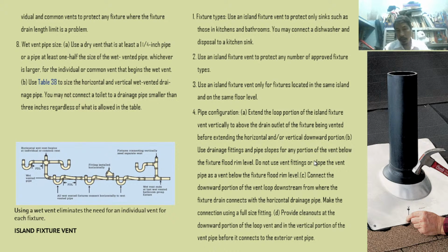Use an island fixture vent only for fixtures located on the same island, the same floor level. Only on the same island. If there are so many fixtures on that island, you have to connect them all without regard to the number of fixtures. But don't connect it to the other island. On the same island alone.